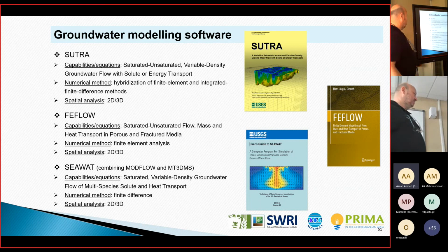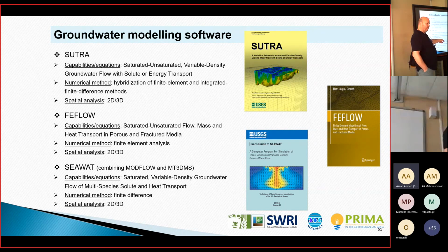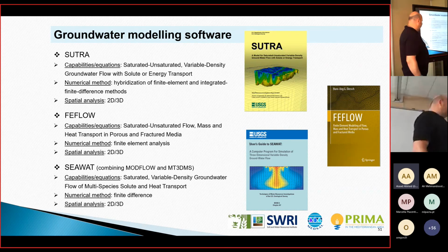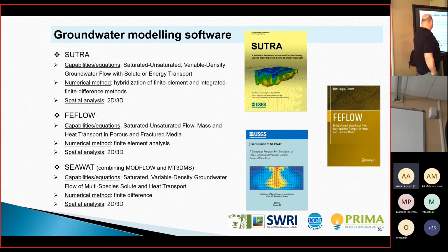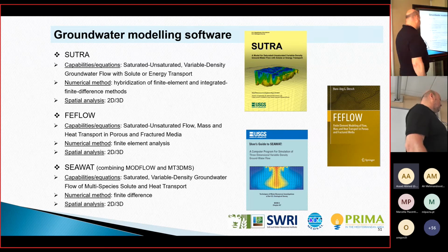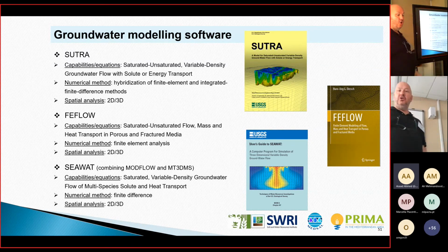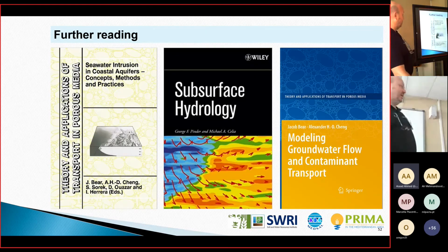And SEAWAT is a model that actually combines the capabilities of MODFLOW and MT3DMS. It simulates saturated variable density groundwater flow with multi-species solute and heat transport using finite difference methods in 2 and 3 dimensions. Also public domain software by USGS.